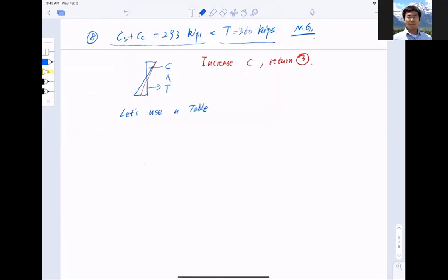Okay. Think like a computer, right? Think like a computer. So let's list on the left hand side that's my compressive zone C. And next column, I'm just going to compute epsilon s prime. And the equation is (C minus ds prime) over C, and multiply epsilon cu.